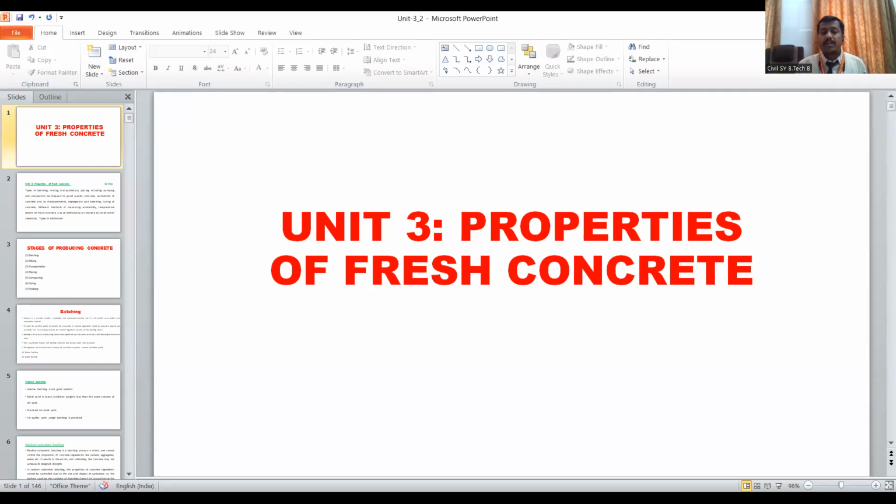Basically, the potential strength and durability of a given concrete mix, that is your concrete mix proportion, is very much dependent on the degree of its compaction. It is very correctly and very rightly said. I think everybody will agree with me. Definitely the strength and the durability always depend on one important factor, nothing but the degree of compaction. How you are going to compact the concrete.